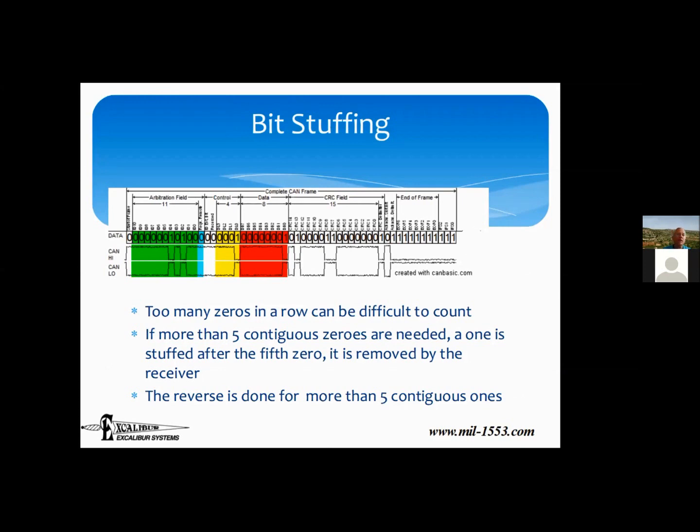And we saw here that CAN bus is one of the simpler ways. High is a 0, low is a 1, or on the redundant bus, it's the reverse. There's a problem with this method, which is namely that, let's say a single bit is a microsecond, right? There are actually about 8 different speeds used in CAN bus. A microsecond is one of them, it's the fastest one. So if this is high for a microsecond, I know I have a 0. If it's high for 5 microseconds, I know I have 5 zeros. The problem is, how do I know how long a microsecond is?